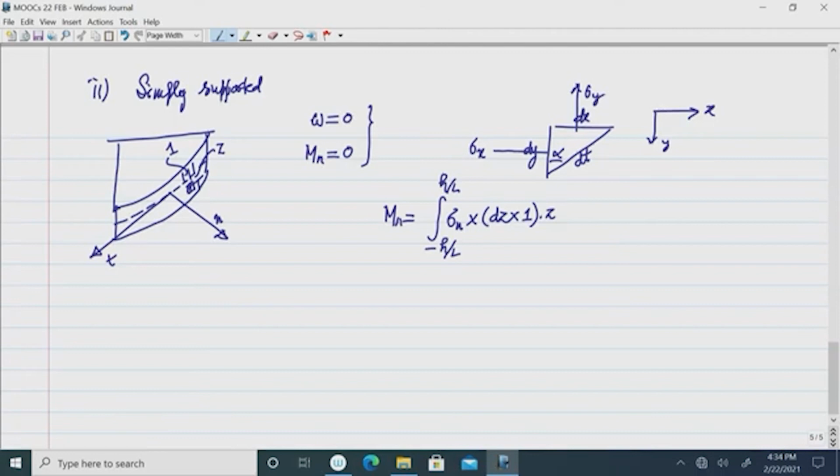Then you have shear stress on the two faces, tau x y, and another shear stress along these faces, tau y x, or tau x y, because these are the same. So, let me write tau y x. This is my element on the curved boundary, because for a small element, the curved length and the straight length are the same. So, I have taken dt as approximately equal to the curved length.